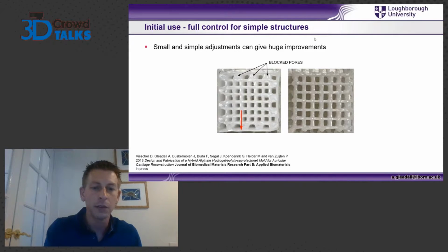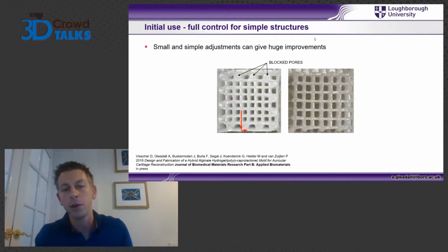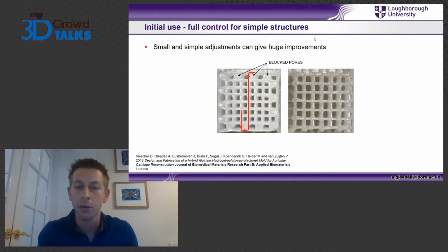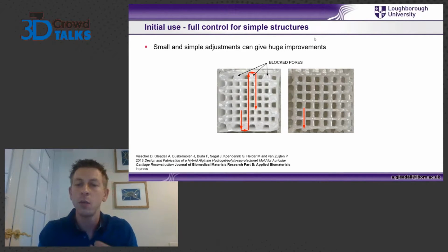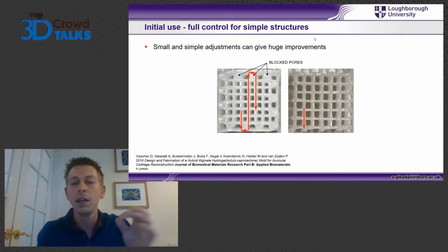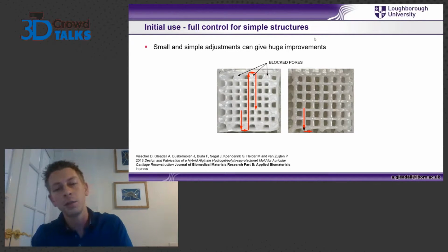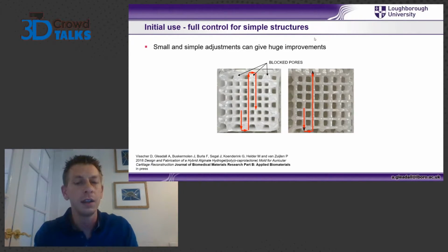What it's doing is the nozzle's coming down to the end here, then going across, then going to the other side, then across, and then down. So as that nozzle is moving across, it's dragging that material, over-extruding at those locations. And I could see from this, there's an easy way to solve that, if you have the control, which is to just, when we get to the edge, take a tiny little step further, and then come across, then go to the other side, take that little tiny step further, and go across and back.